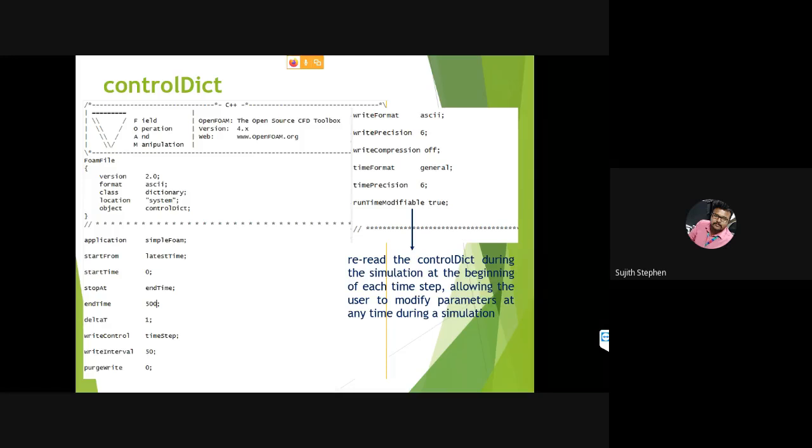Yeah, and in that particular case, that might be a problem with the mesh, so either we want to change the mesh elements. Actually, I used exactly the same mesh for both simulations. One with MSH and the other I converted from MSH to OpenFOAM mesh and tried the same settings. But since the numerical schemes are different in ANSYS and OpenFOAM, we may find this difficulty. So generally, what we do is either we reduce the time step, or we refine the mesh. I tried reducing the time step and it worked fine.